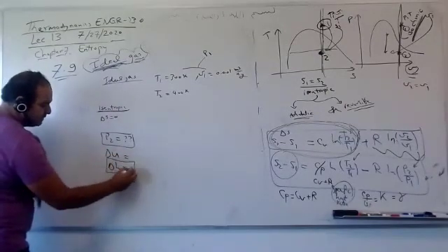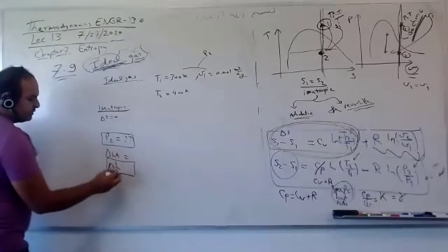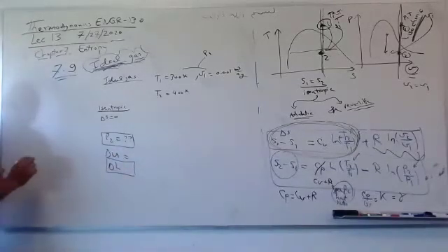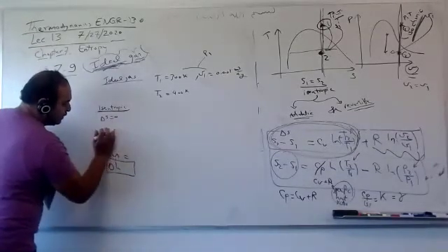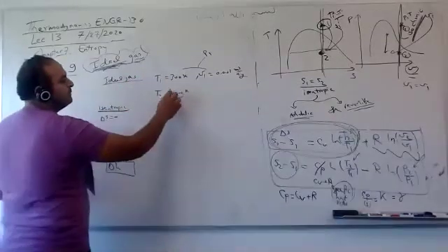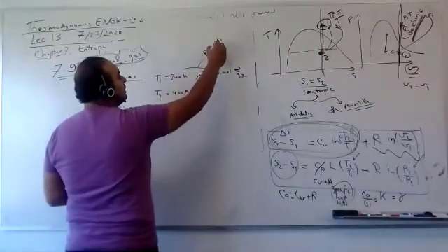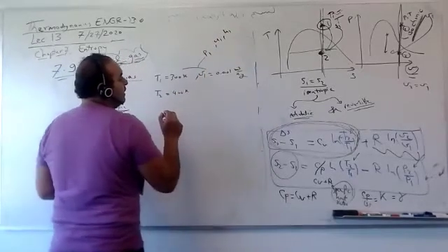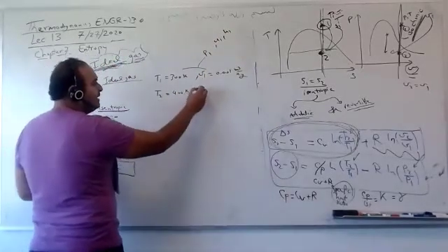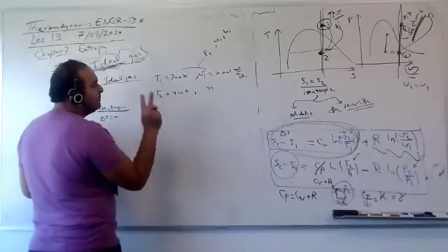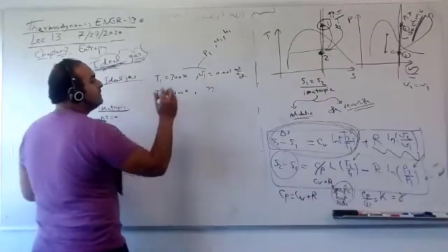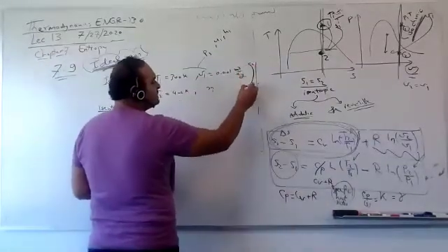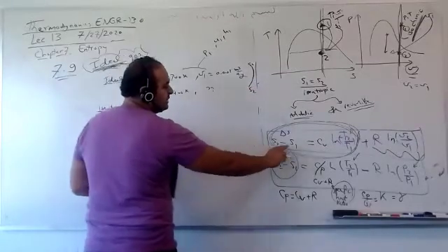Sometimes we need this. Because if it's a compressor or turbine, we need delta H. Let's say I want delta H. You can easily obtain P1, U1, and H1. But when you go to 2, you don't have anything else. You need two independent intensive properties. But you can use S1 equal to S2. You can put it here.